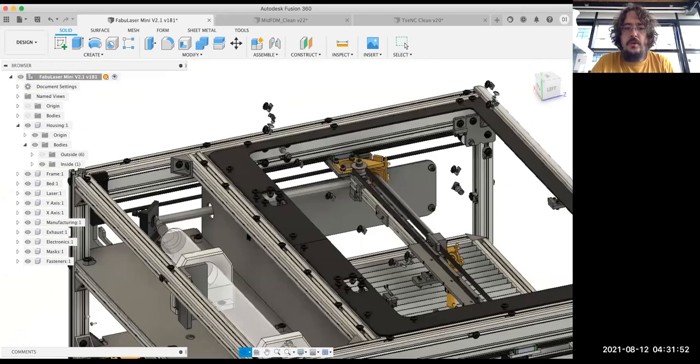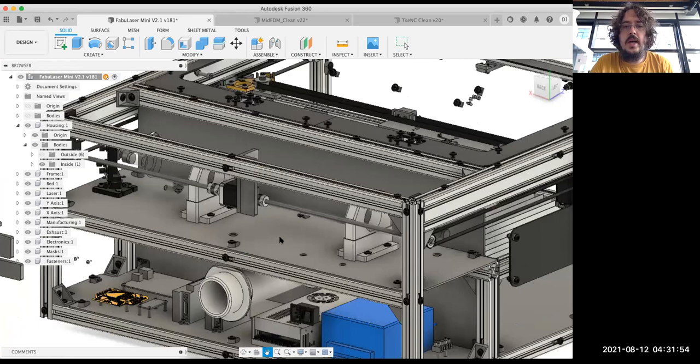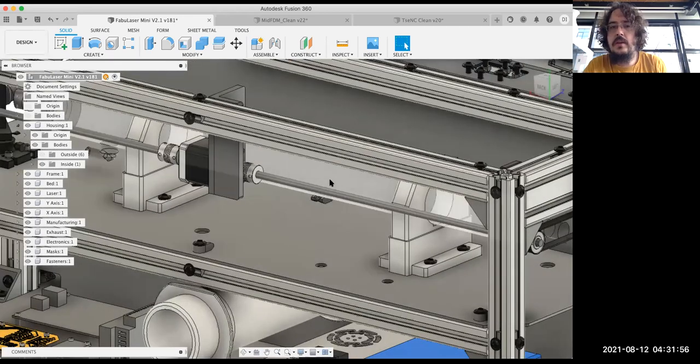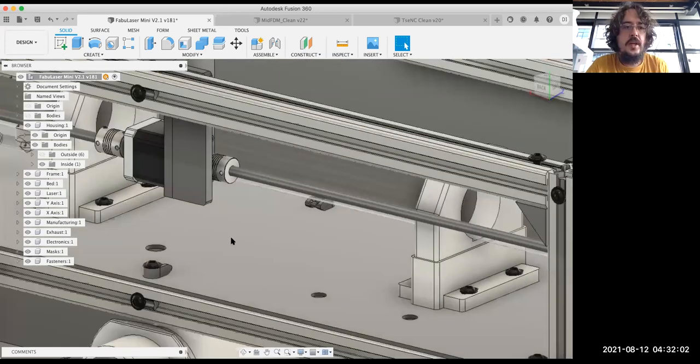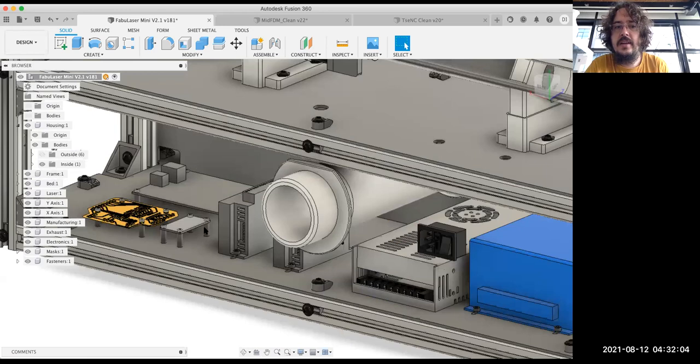Okay, just to conclude, we have further safety features. We have a water flow sensor that will not shoot the laser if the water is not flowing, so it's automatically controlled. We have this relay that will shut off the laser in case something happens. So for example, if you trigger the hand stops, the laser will be shut off. If the microcontroller is broken, this will detect it because maybe the voltage is crazy and so on, and this will stop the laser immediately from firing.